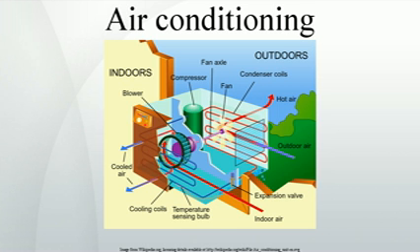Since evaporation occurs when heat is absorbed, and condensation occurs when heat is released, air conditioners use a compressor to cause pressure changes between two compartments, and actively condense and pump a refrigerant around. A refrigerant is pumped into the evaporator coil, located in the compartment to be cooled, where the low pressure causes the refrigerant to evaporate into a vapor, taking heat with it. At the opposite side of the cycle is the condenser, which is located outside of the cooled compartment, where the refrigerant vapor is compressed and forced through another heat exchange coil, condensing the refrigerant into a liquid, thus releasing the heat previously absorbed from the cooled space.